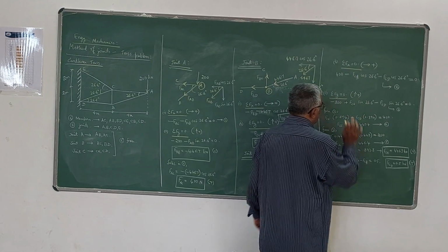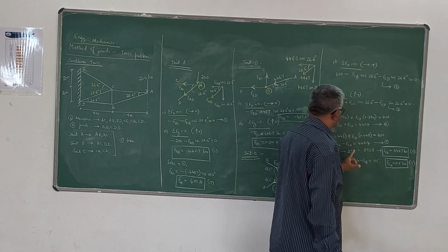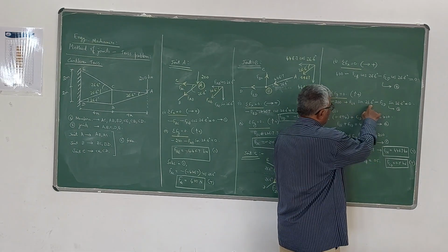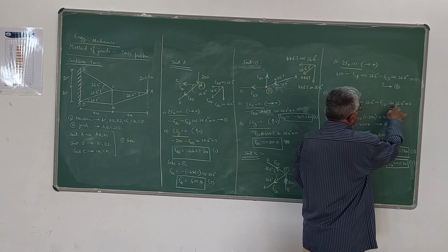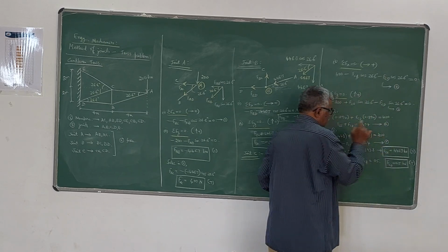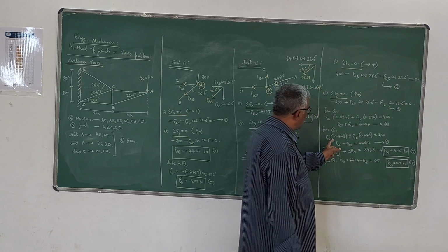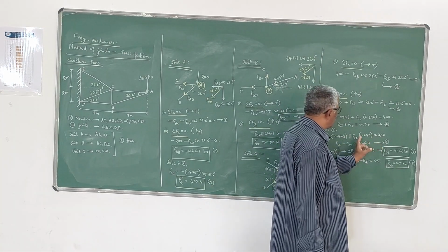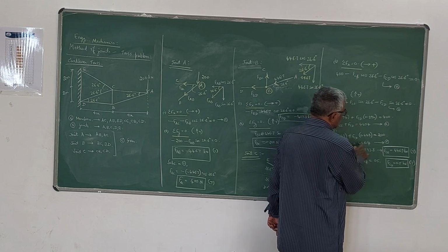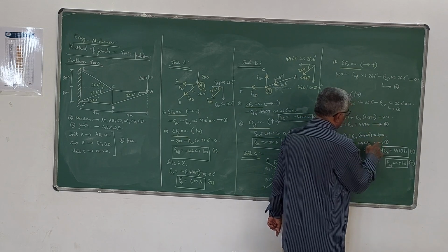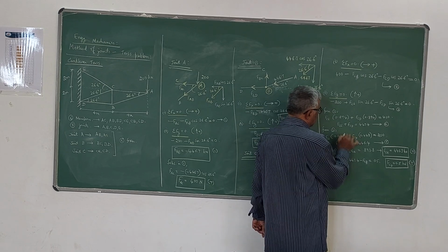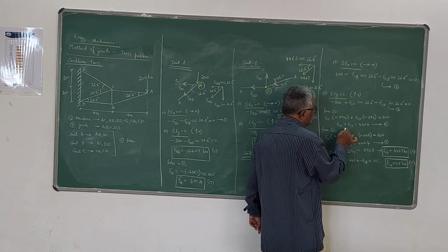Similarly, equation 3 can be written with sin 26.6 degrees, which is nothing but 0.448. So this is FCE into 0.448 minus FCD into 0.448. This 200, if you bring to RHS, becomes plus 200. Dividing once again by 0.448 on both LHS and RHS, you get FCE minus FCD is equal to 200 divided by 0.448, which is nothing but 446.4. So these two equations have been reduced to this form.